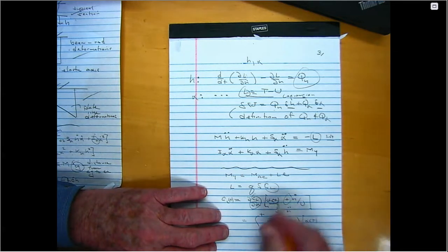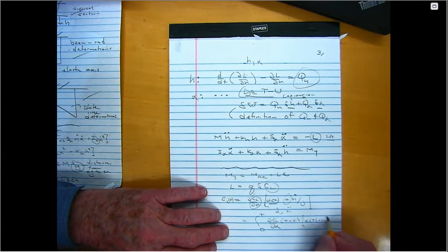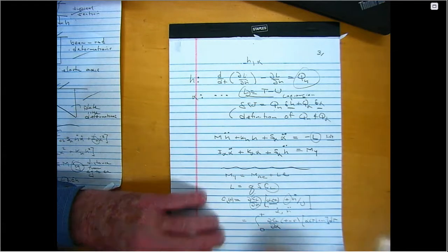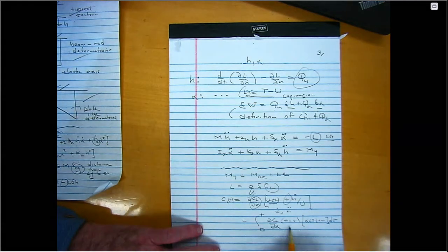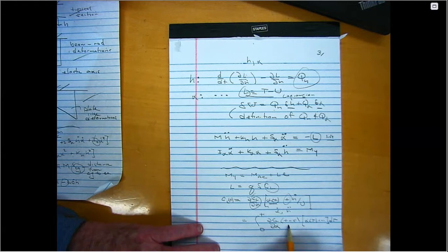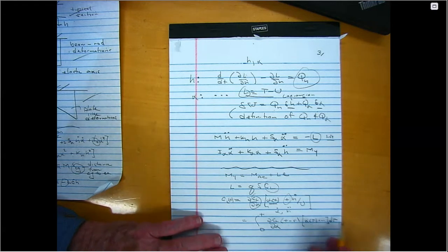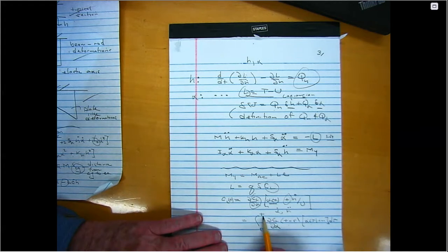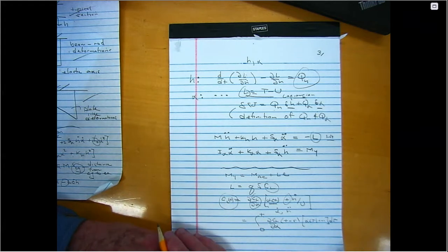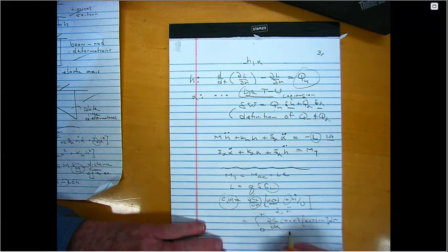I could also include the H dot, which I won't bother. What does this say? There's some function of time such that when I multiply it by alpha at time tau, and I sum up all the contributions of alpha from the time when motion began up to the present time, that contributes to the present lift. This is a convolution.